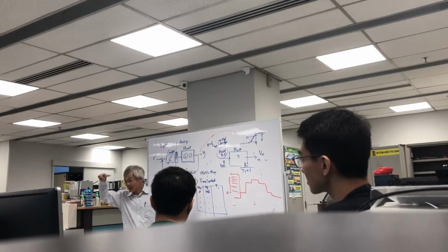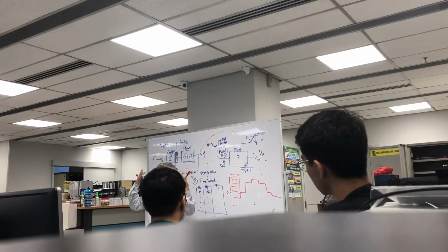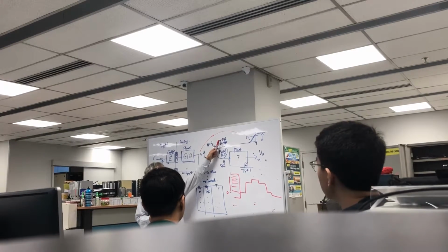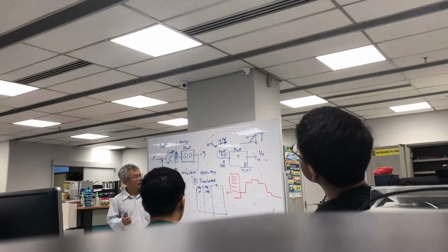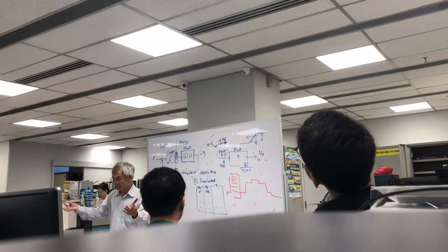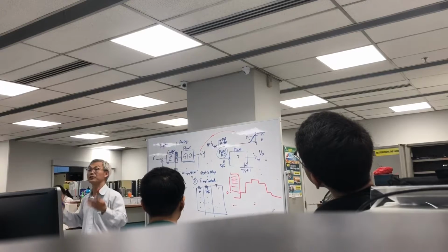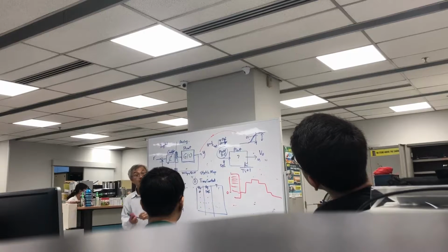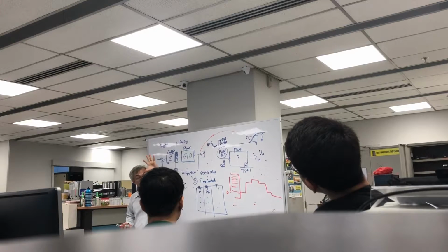We'll do the step test. Just now we discussed, right? There are various ways, various considerations to do the step test. Where do you start? Where do you end? Means how big is the step? I want to let you see for yourself whether this is the case or not. I'm talking in general, but we use this as a case study. So you should try to do step tests at different operating conditions, different step sizes. Then you see for yourself, you record, you draw it out, or you take a picture.